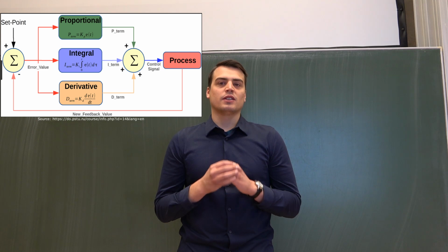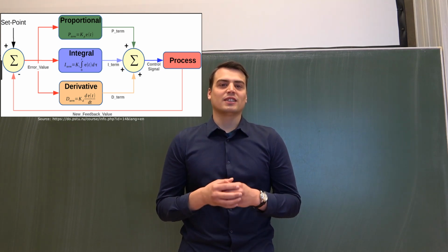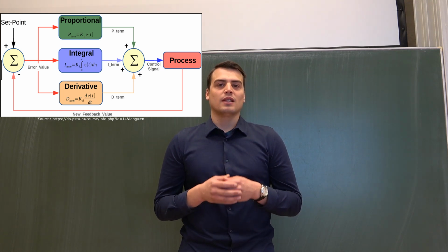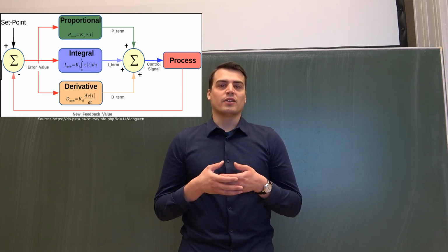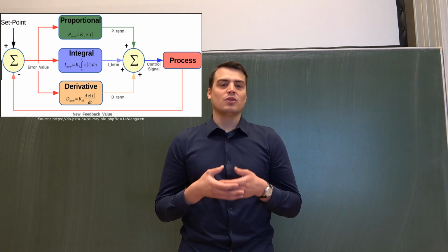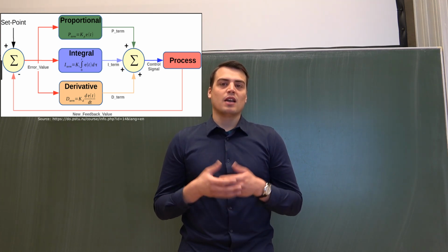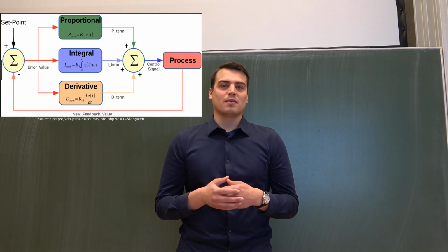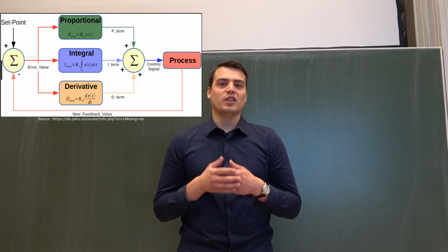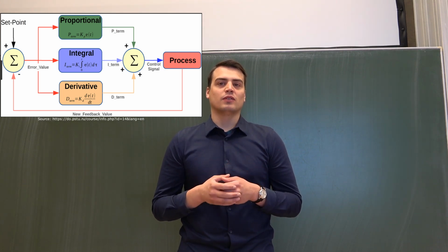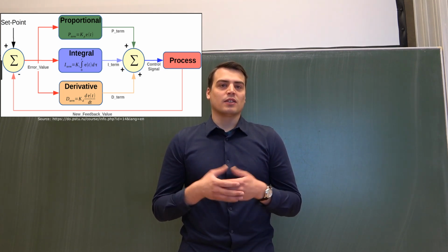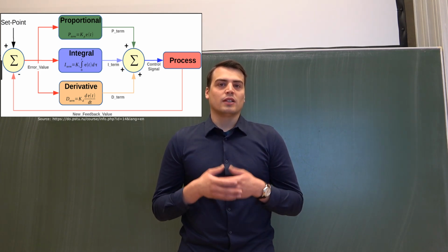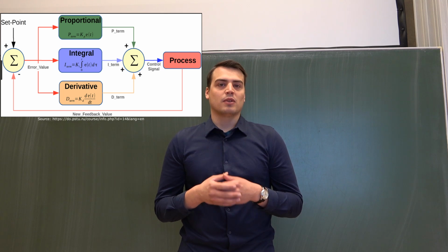The larger the derivative time, the stronger and faster the system reacts to changes in the error term. In an ideal case, where there is no noise, it's useful to use a large derivative time. However, unfortunately in reality, there always exists some noise. Because of this problem, we need to balance the value of this parameter, because if it's too high and the sensor response is noisy, or the control loop rate is too slow, then the system can become unstable.